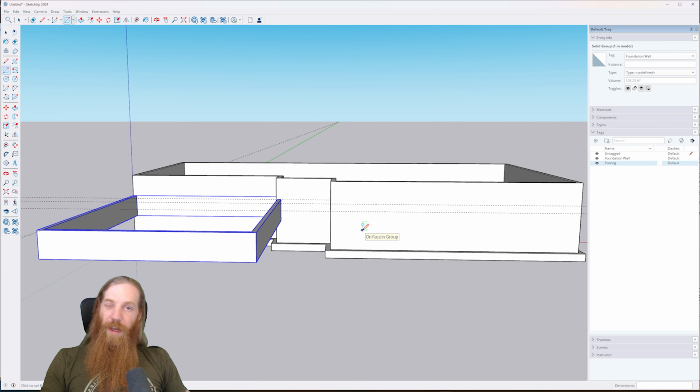So another reason I like having a few feet of foundation wall above grade for the home is because I live in a high elevation environment. So that means we get a lot of snow, right? We're up in the mountains. In the winter, you could easily have 3 or 4 feet of snow up against your house. And the idea is to try and keep as much of that snow as possible off of your siding, right? You don't want it piled up against your siding on the house. That's going to create advanced decay of your siding.